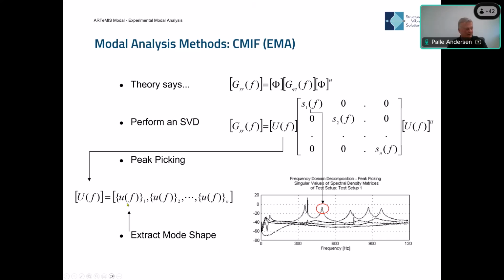So this is basically the way it works. This is the way we get the initial mode shape estimate that we need for further processing. There is one little thing to keep in mind here, but it's not something that you need to think about so much, because the software has to do it for you. We are always using the left singular vectors. That means when we use the singular value decomposition on an FRF matrix, it's a little bit important what we have in the row space of this matrix.